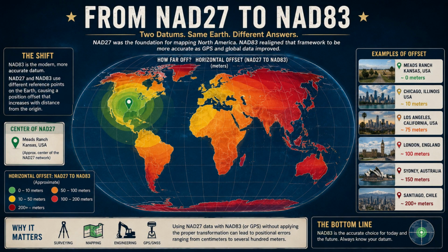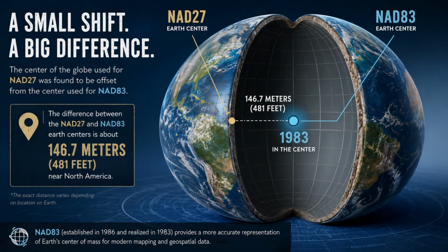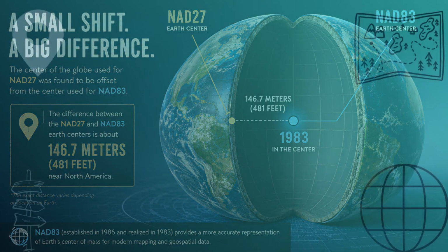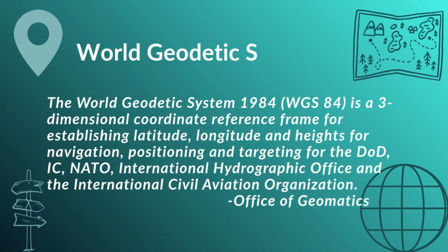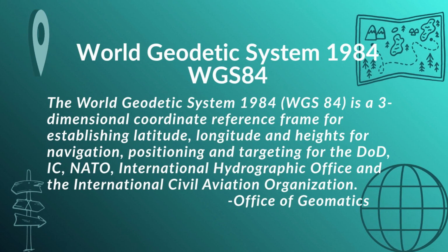And there's also WGS-84 mentioned in the sources. The World Geodetic System of 1984. It is the default for modern GPS and is functionally very similar to NAD-83, though. They have drifted apart slightly over time due to tectonic plate movement.